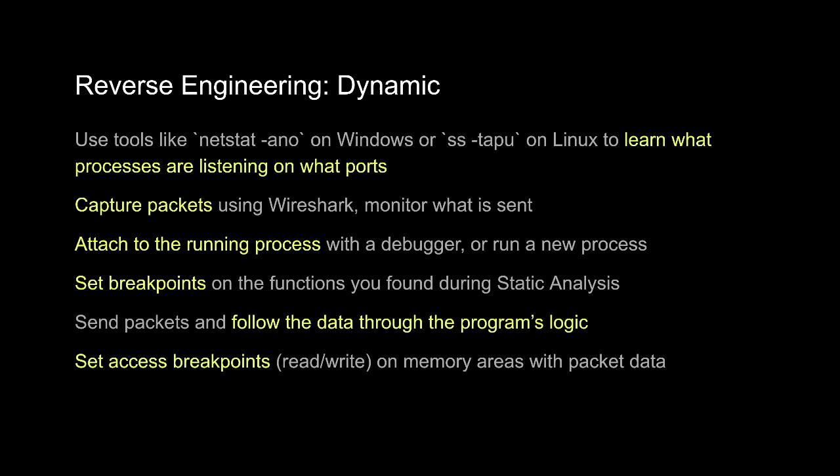Another big thing is if you set access breakpoints, which are breakpoints that are triggered when you read, write or execute from a certain area of the program image. Those are really useful for packet stuff, because if you know where the packet buffer is and you want to see which functions are manipulating data within a known packet buffer, those will typically tell you what things are accessing packets. It can be really helpful because some software is really complicated in how functions are called, and instead of wasting time understanding all that machinery, you want to get to the real meat of it. That's typically what I try to do.